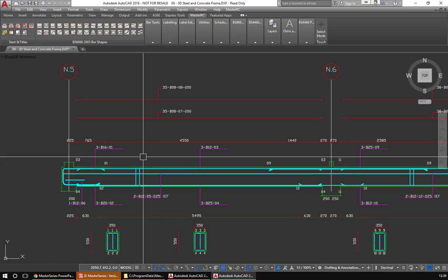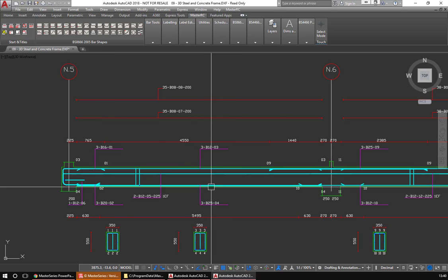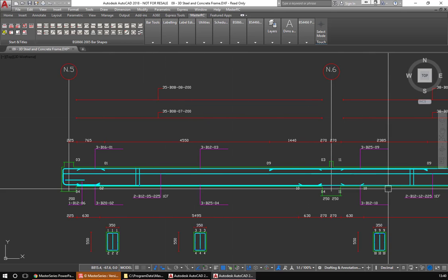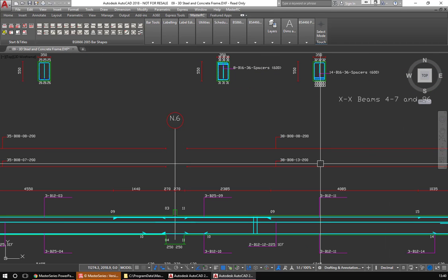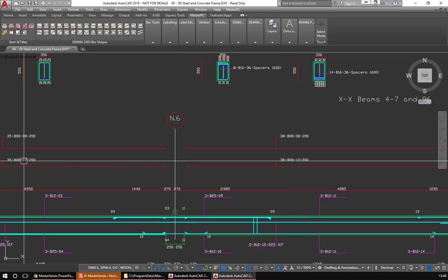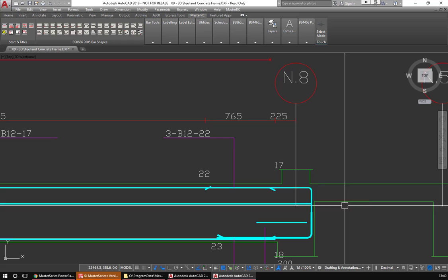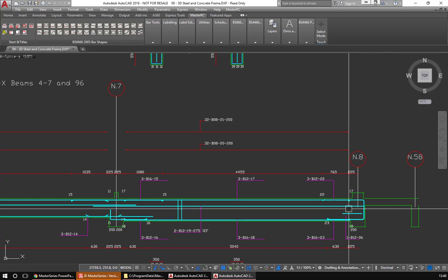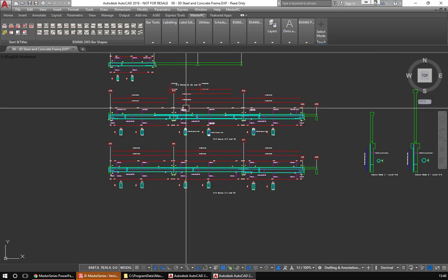There we go. So there we have our B16s, 01, and our B08s for our links. And you'll notice that we will end up reusing bars as and when we need them. So 08s have been used here and here, but this is 7s, and these are different because it's a different width of section. And then we have a little bit out here that is actually not concrete, that we don't consider. Actually, that's part of that cantilever for the entrance.